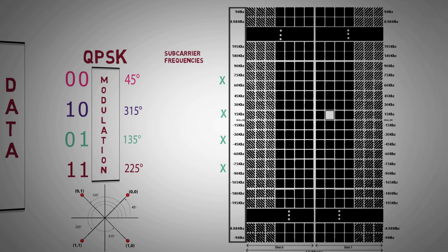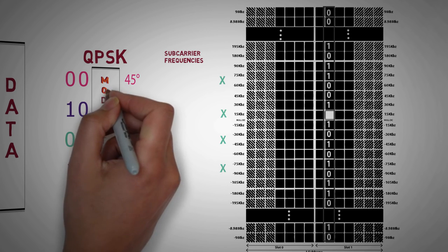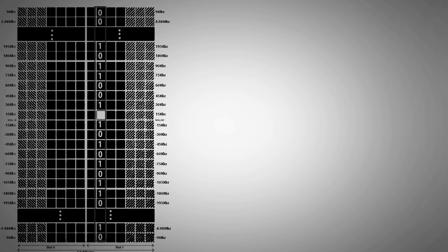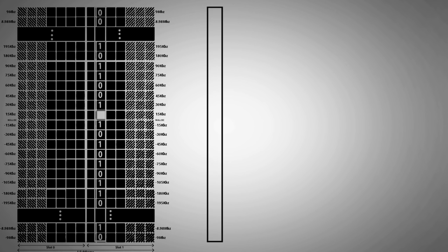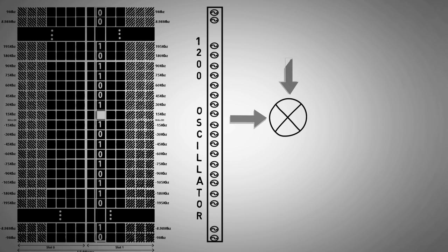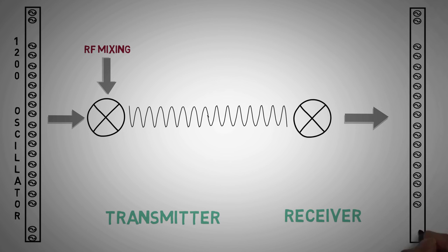Thus, in a 20 MHz channel, all the 1200 resource elements carrying 1200 symbols over 1200 subcarriers are modulated with the appropriate modulation scheme. Now, since the data is modulated over 1200 subcarriers, a transmitter will require 1200 oscillators for its generation, and another 1200 will be required by the receiver for proper demodulation.